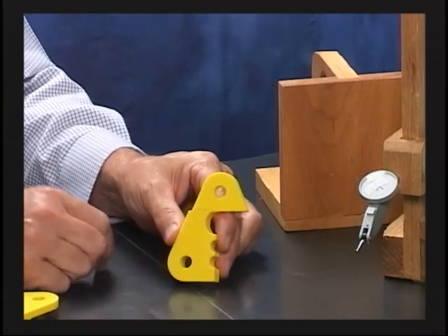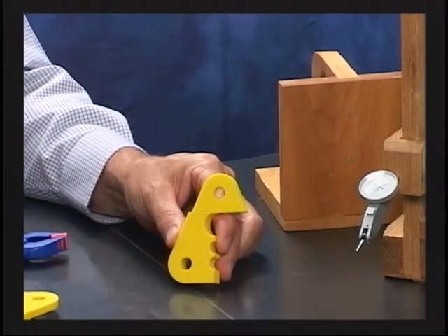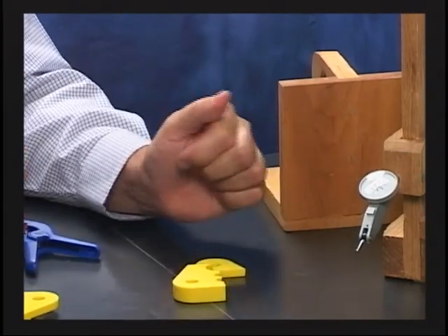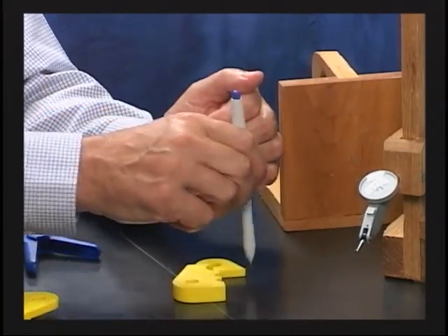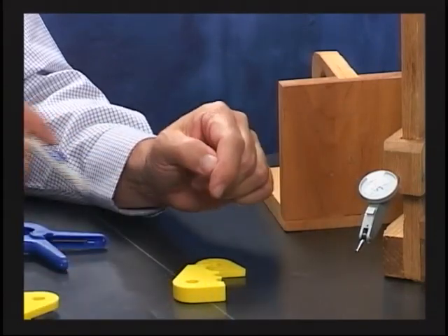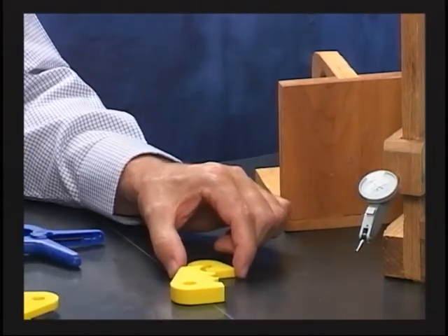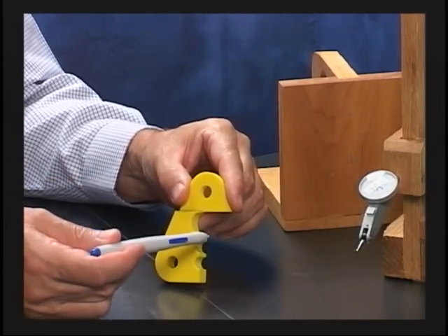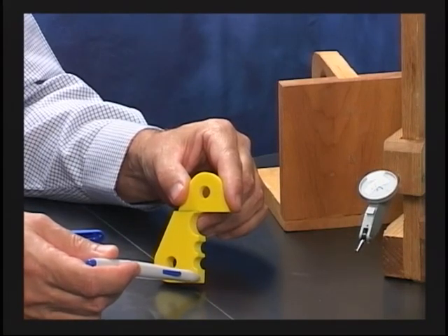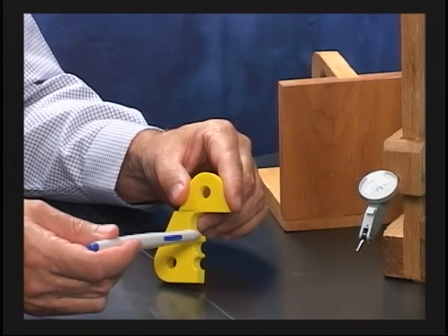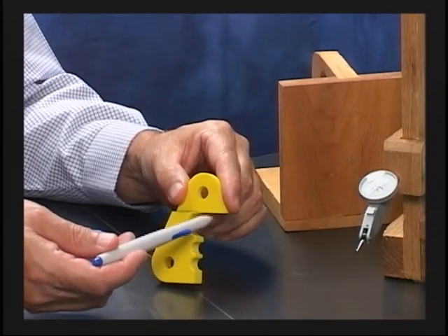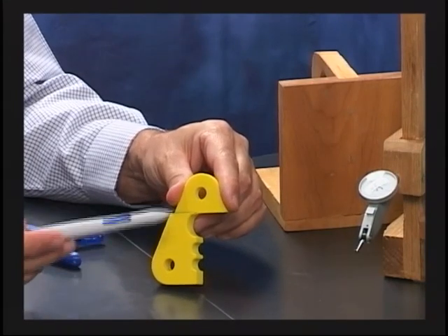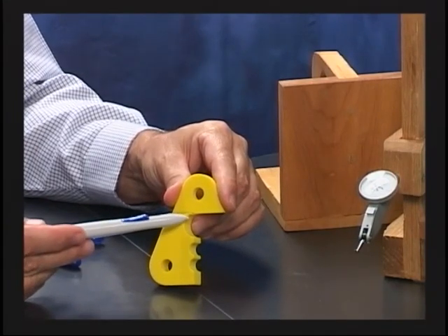Now, if you're going to measure this thing with a coordinate measuring machine, I don't know, they might just lay the thing down on the table. If they came down on the table, I would touch my 0 on this back face and establish a plane. Once I establish a plane, now I have to come in with my secondary datum. Probably what they would do to establish the secondary datum is touch the surface a minimum of 2 points. You probably have to touch more than 2 points and establish a plane, and then touch a minimum of 1 point and establish a plane. And then once they did that, they would find an origin just like we did here a minute ago on the angle plate and surface plate.